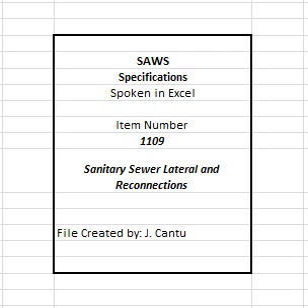D. Test each lateral connection before backfilling. E. Embed the lateral pipe and point of connection, as specified for the sanitary sewer main, as shown in the contract documents. F. Place and compact trench zone backfill in compliance with specification item number 804, excavation, trenching and backfill.